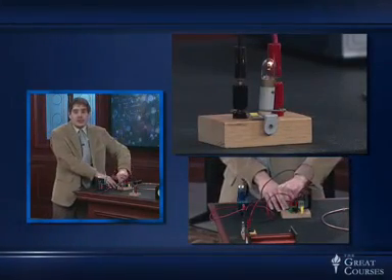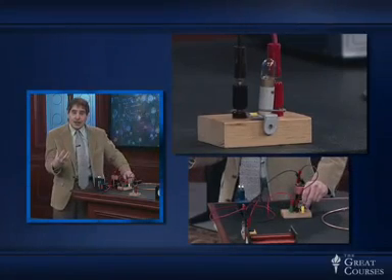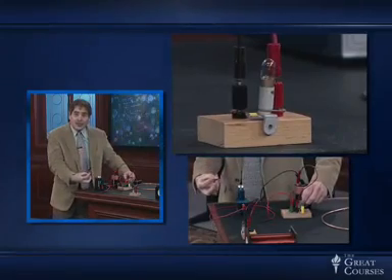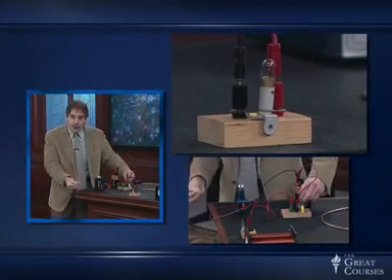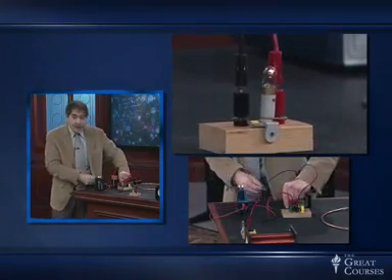I'm going to open the switch. And you see the light bulb flash instantaneously as I open the switch. Where did that extra voltage and current come from? It came from the inductor. It came from the collapse of the magnetic field and the induced voltage that occurs as a result of that. And that's what could, in fact, be dangerous in some situations.